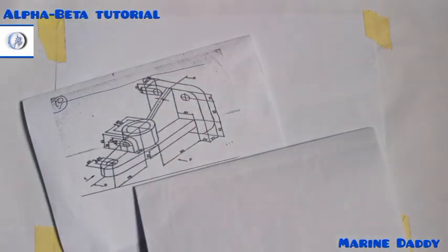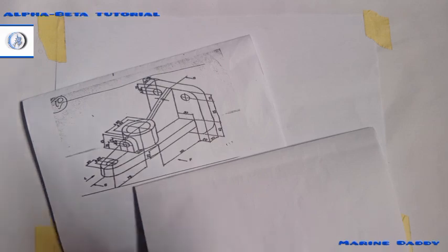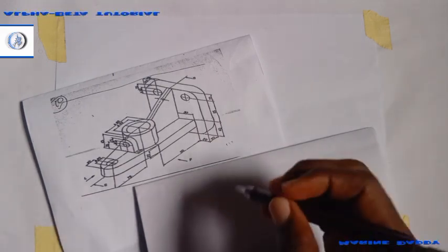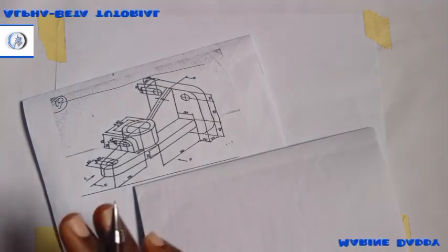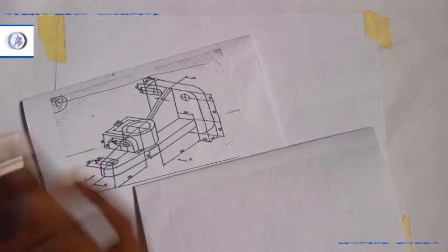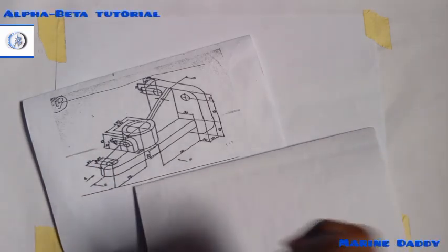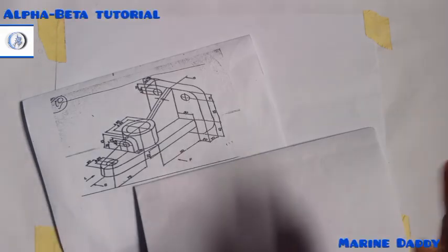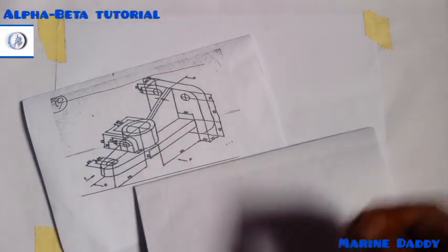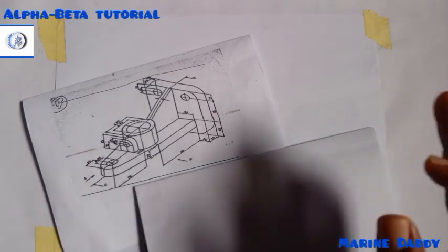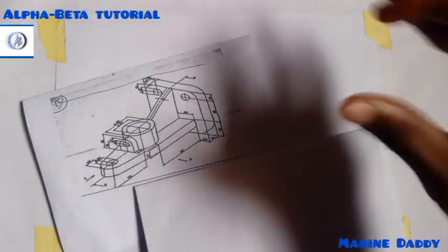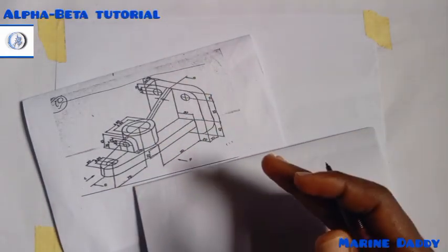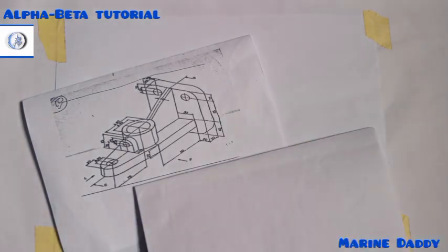So looking at this diagram now, we have been asked to convert this into an orthographic projection, a first angle projection. Before we even place the views in the progression they're supposed to be in, the first thing I usually tell my students is to draw a sketch of it, the three views, how it's supposed to look, then put the dimensions there. Those things you end up doing will give you an insight on how to actually draw the diagram on your answer booklet.